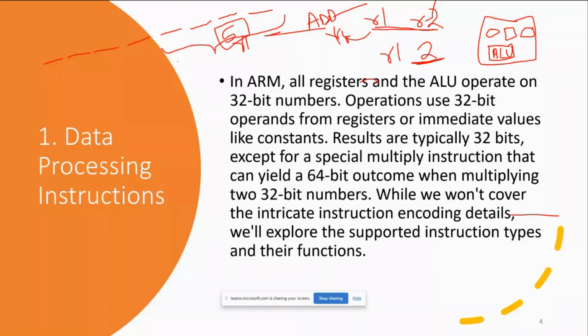You will also study a certain microprocessor in your course, like 8085, where the register size is 8-bit. But if you have to store something of 16 bits, we use register pairs, 8 bits stored in one register and another 8 bits in another register. Similarly, here in ARM we have two versions of multiplication.